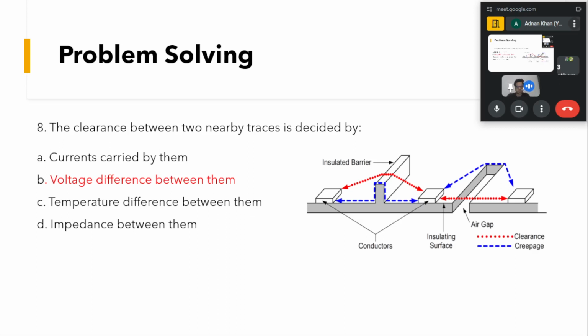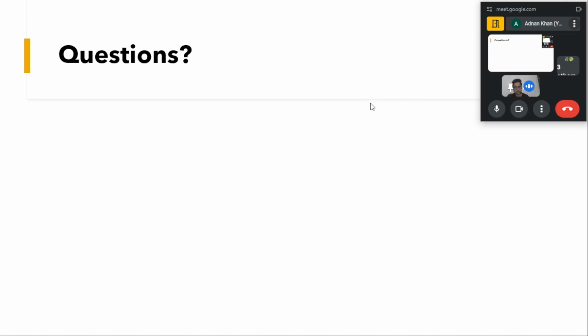As you saw, we touched every aspect of designing a particular power converter, be it choosing the devices, power levels, gate drivers, thermal management components, or designing the inductors and capacitors, how to choose them, how to design them, and then how to design the PCB, and so on. This usually covers the major portion of designing a particular converter.